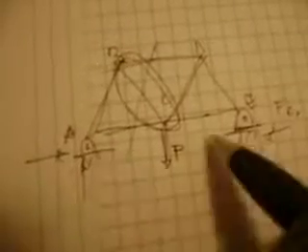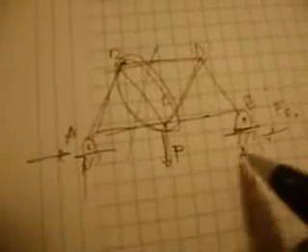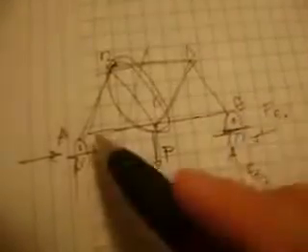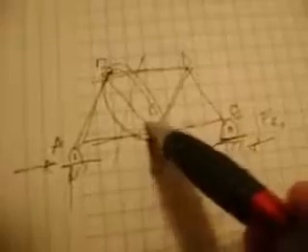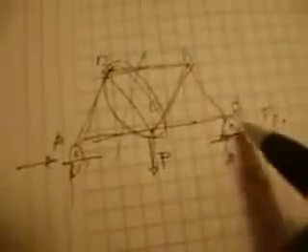How do you do that? If you take a sum of forces in the y direction, you will get two unknowns, and you won't be able to solve it. So you take a sum of moments at E or A. In this case, because we're looking for this component, we're going to take a summation of moments at E. So we make the summation of moments at E equal to 0.